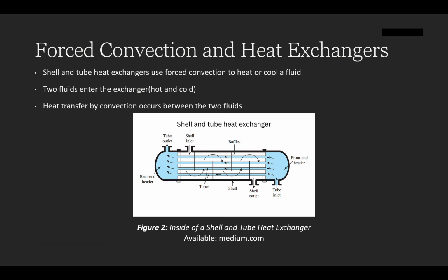These heat exchangers offer advantages such as easy maintenance and repair. They can be used in multiple different applications. They can handle high amounts of pressure. Figure 2 displays an image of the inside of a typical shell and tube heat exchanger. Two fluids flow throughout the exchanger and use convection to transfer heat from one to another. The fluid that is more likely to foul the walls flows through the tube side since it is easier to clean than the shell side. The number and length of the tubes and the number of times the fluid passes through the tubes is dependent on the situation.